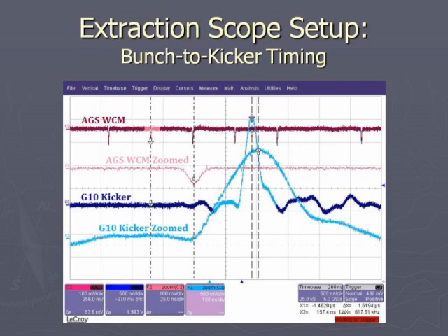That can happen sometimes. If you have a lot of jitter, it's typically a synchro issue, and very often it will hop by 20 nanoseconds, so you get 2 modes, one over here and one 20 nanoseconds apart from that in either direction. And that typically means that you have this race condition. So 20 nanoseconds is approximately a RHIC RF bucket, so we're aiming at the wrong RHIC RF bucket. And low-level RF can change the phasing of 2 triggers such that they're not hopping relative to one another anymore. But that's a pretty reasonable signature. A 20 nanosecond jump is a pretty reasonable signature that you have that race condition issue.